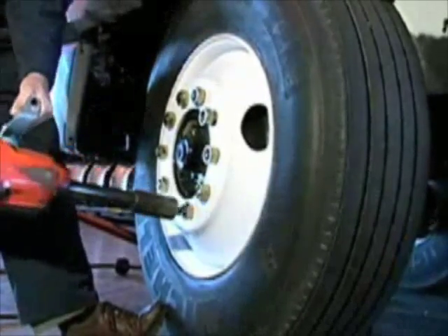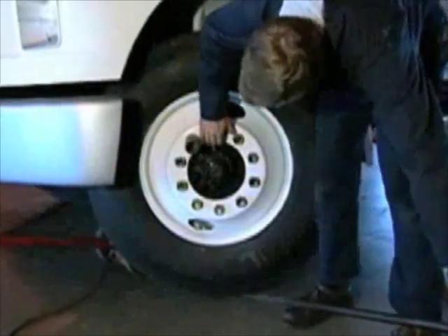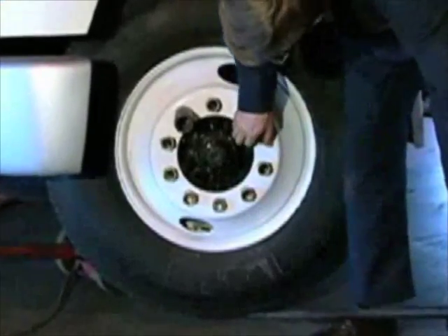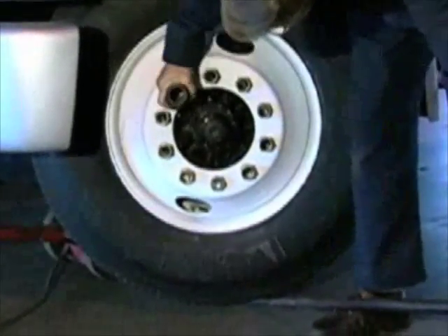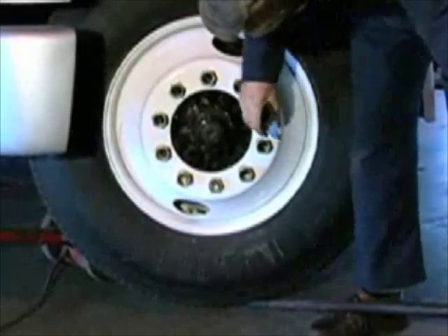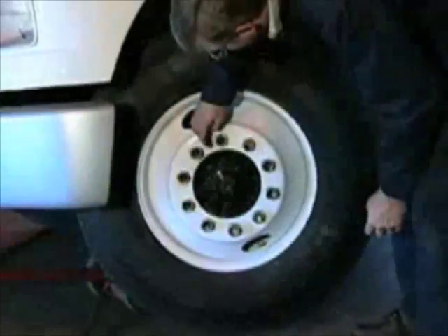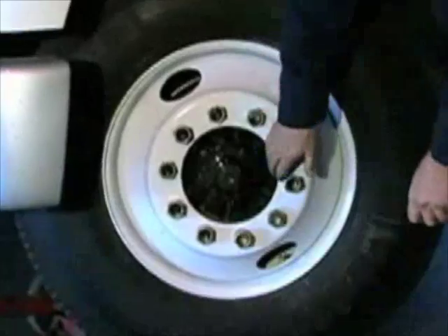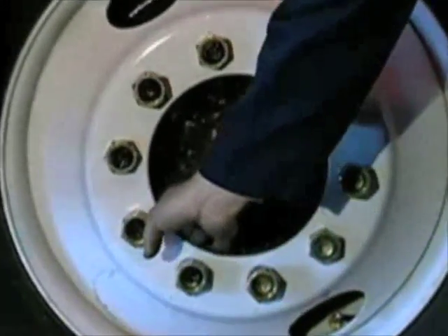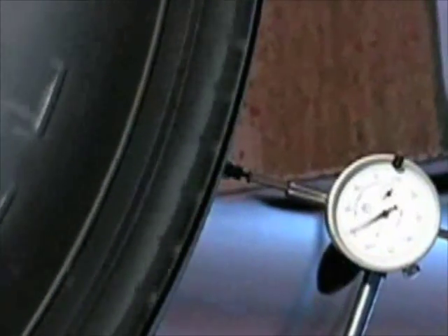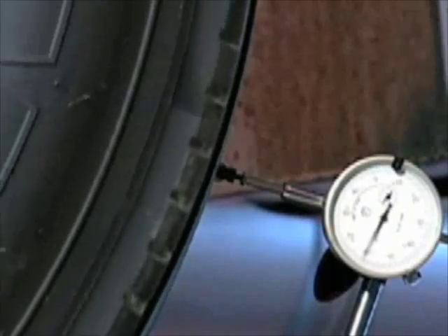This is accomplished by loosening the lug nuts. Lift up on the tire wheel assembly with a tire iron and feel around the center bore of the wheel and brake drum. When it feels even with your finger, hand tighten 3 of the lug nuts in a triangle. Hand tightening using the lug nut socket will accomplish this job easily. Once the 3 nuts are hand tightened, feel around the assembly for an even placement of the brake drum and wheel at the center bore hole. If the assembly is centered, proceed to tighten the nuts in accordance with vehicle and wheel manufacturer's specifications. Recheck the radial and lateral runout to see if any improvement was made.